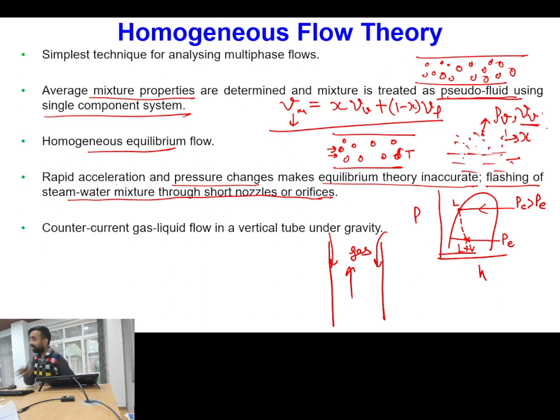Yes, we can use inside a boiling tube. This is used. We will see. Heat exchange is happening from outside, but within the system during the phase change process, all the liquid is getting converted into vapor at the saturation temperature only. So temperature of vapor and temperature of liquid during the phase change processes are remaining same. So that's why this can be applied for boiler and condenser tubes.